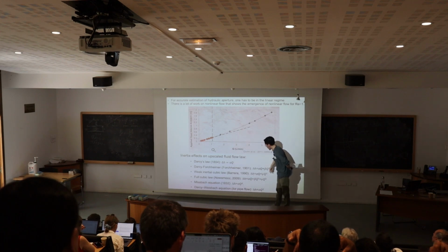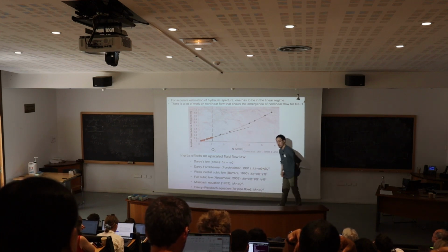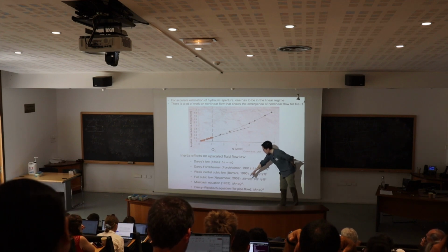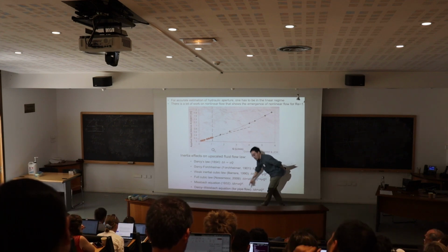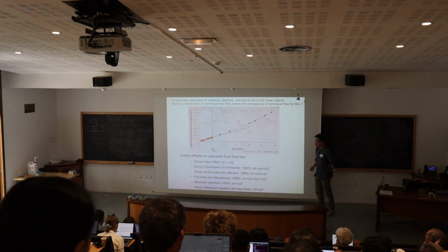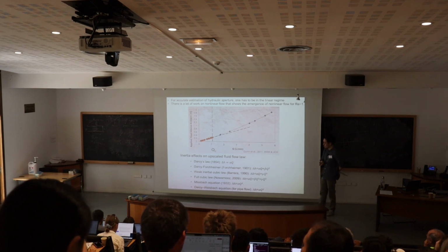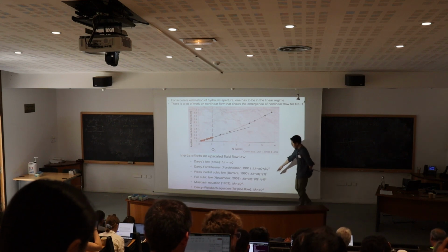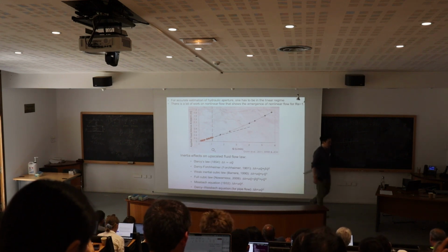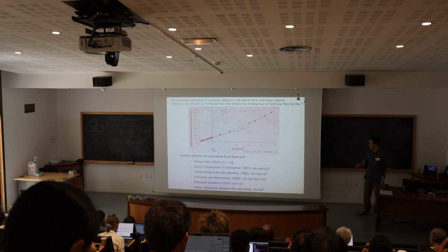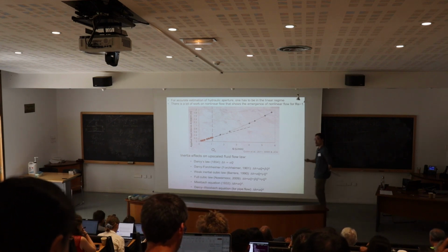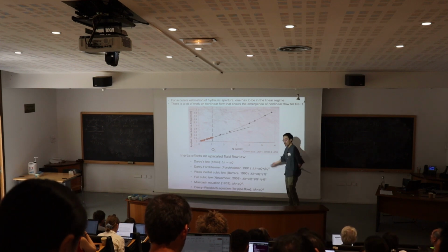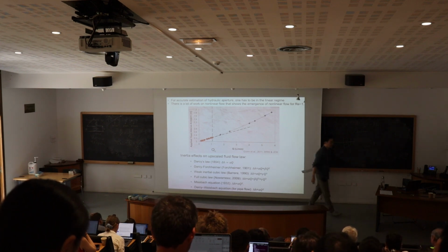And from that, you can predict the relation between head gradient and Q. Okay? And there's another well-known law, the Missbach equation, which is basically just a power law with a fitting parameter for the power. And I know some of you are doing karst hydrogeology, and I believe the most common law is the Darcy-Weisbach equation, which is friction factor times Q to the power 2. So all to say, it has been studied a lot, and there are a lot of references. Of course, there are things to be improved. There are many more recent studies, but they are relatively well studied.